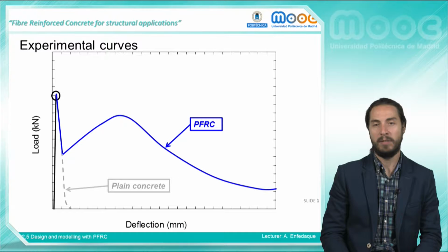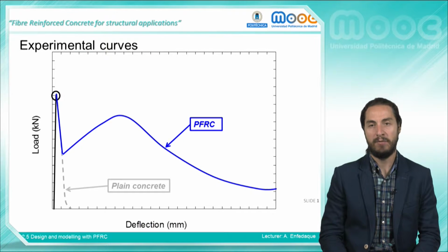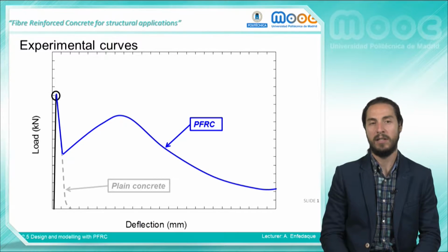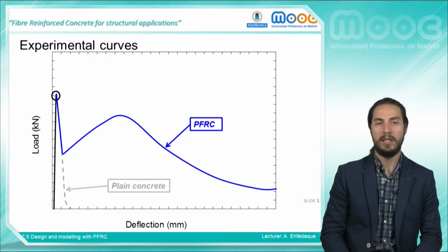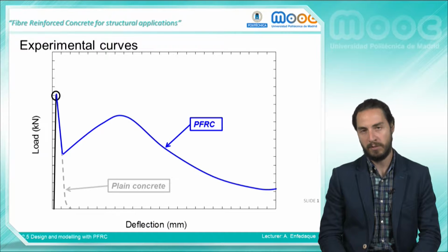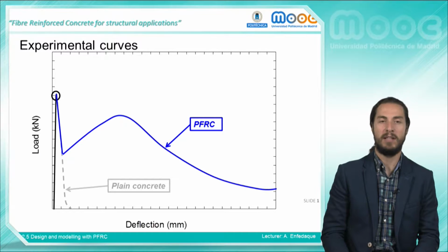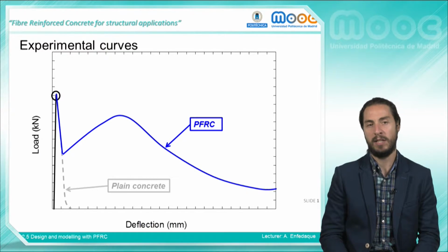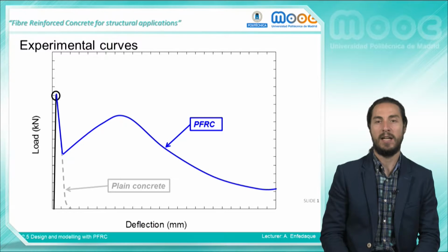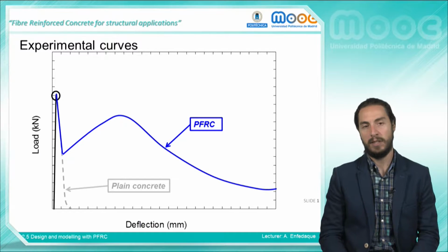However, in the case of the polyolefin fiber reinforced concrete, the influence of the fibers is negligible in the loading branch. However, in the unloading branch of the polyolefin fiber reinforced concrete, the load decreases until reaching a minimum. After this point, the load-bearing capacity of the material increases and a post-peak loading branch starts. This branch ends after reaching the maximum post-peak load, where an unloading starts at a slow rate.